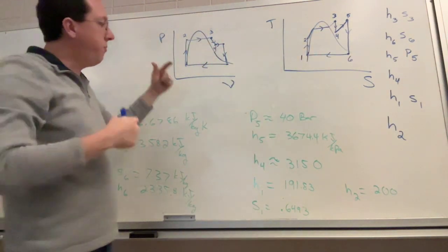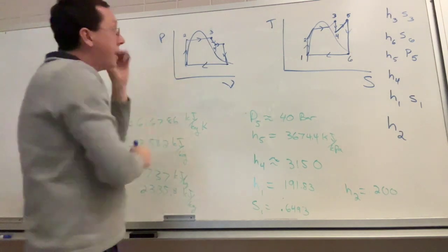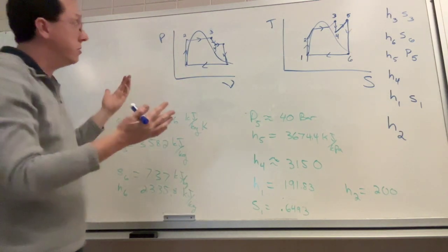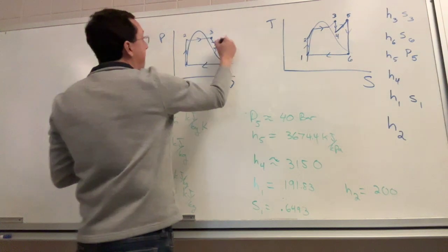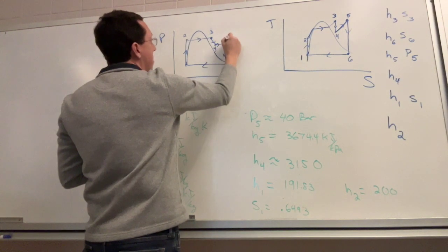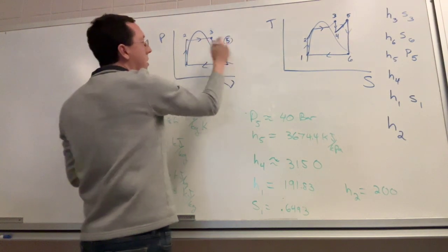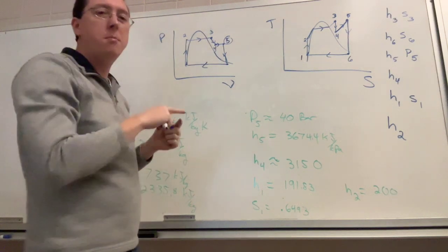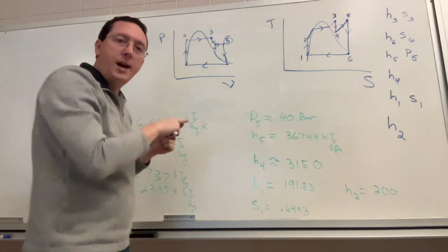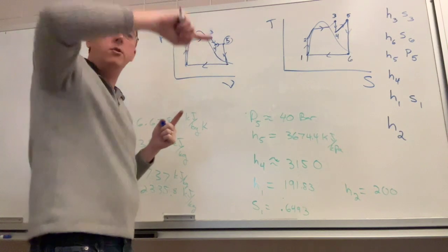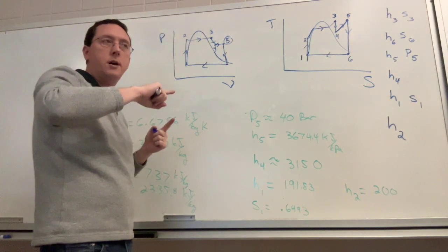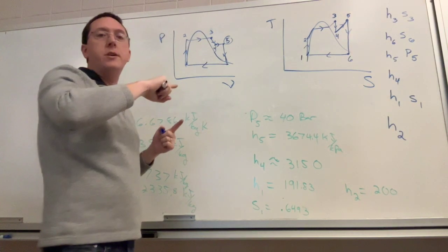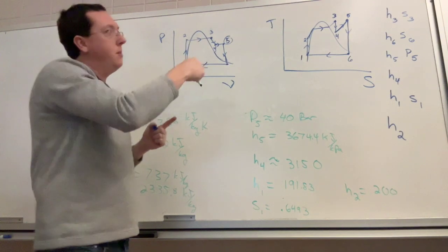And then from 4 to 5 is the reheat back through the boiler the second time. So it's isobaric. So state 5 is connected to state 4 by an isobar. And then the problem told us that after it left the boiler, we assumed it boiled long enough to reach that 600 degrees Celsius number that we had at state 3.